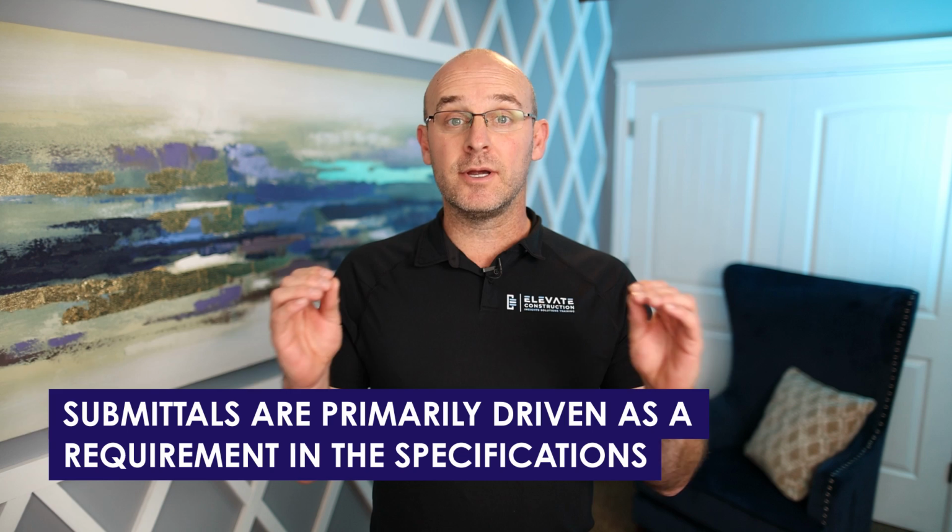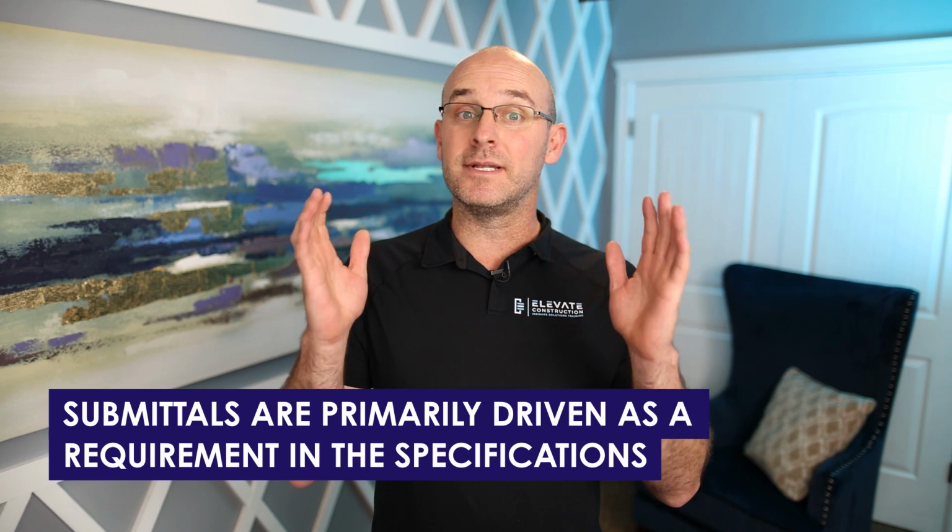All right, so we're going to get right into the steps right now. We all know what submittals are. They are drawings, documents, mock-ups, or samples created by the contractor and presented to the designers to help demonstrate that their proposed plan and materials match the details and the specifications in the contract documents. Submittals are primarily driven as a requirement in the specifications. So here are some of the best practices when it comes to managing the process and creating and reviewing submittals.